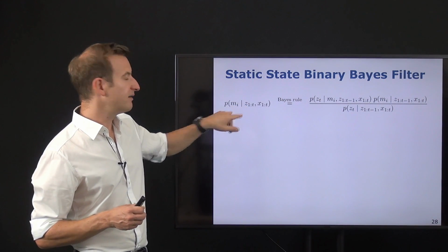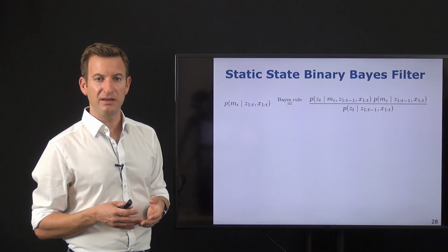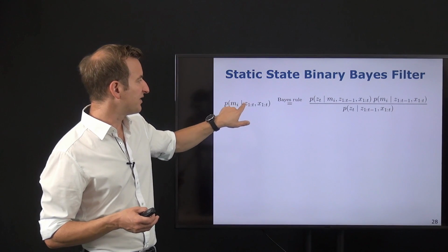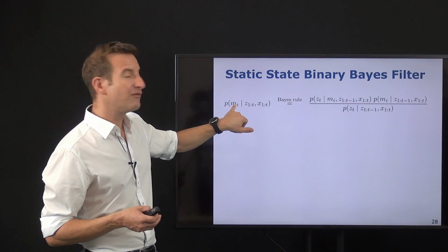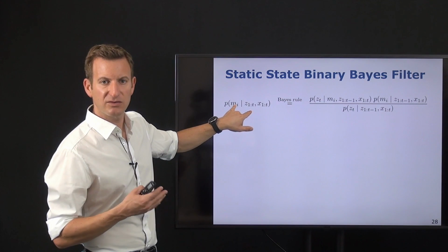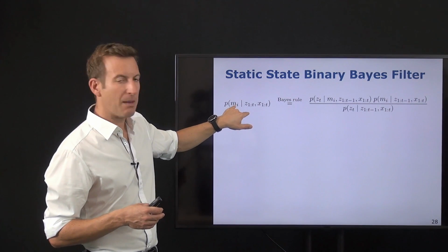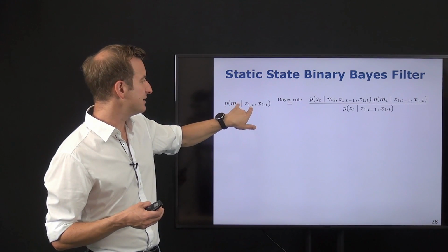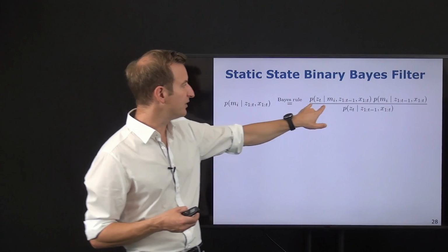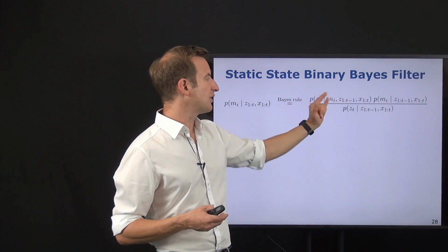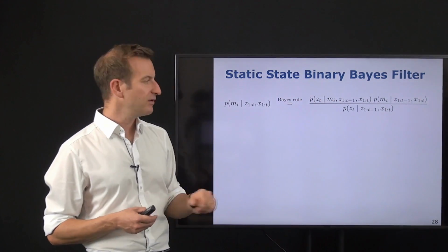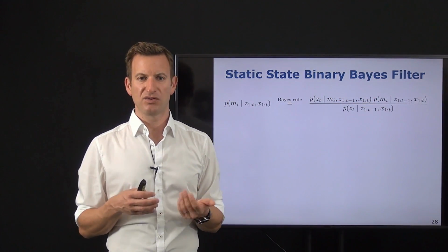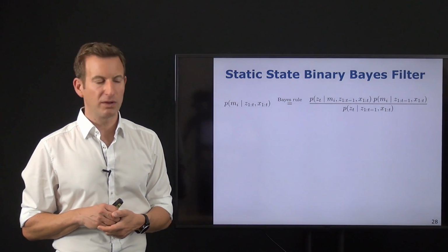And we are, again, similar to the derivation of the Bayes filter in the last lecture, swapping the variable z_t, the last observation, with the variable we want to estimate. This time it's not x, it's not a localization problem, it is m_i, so the state of a cell. So I'm swapping m_i and z_t. Here, m_i and z_t are swapped compared to here. And then we have the two additional terms, the prior and the evidence, that result from a direct application of Bayes' rule using background knowledge.